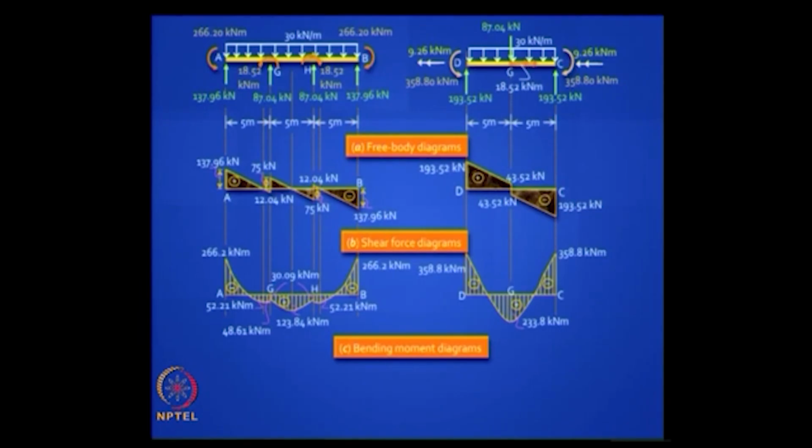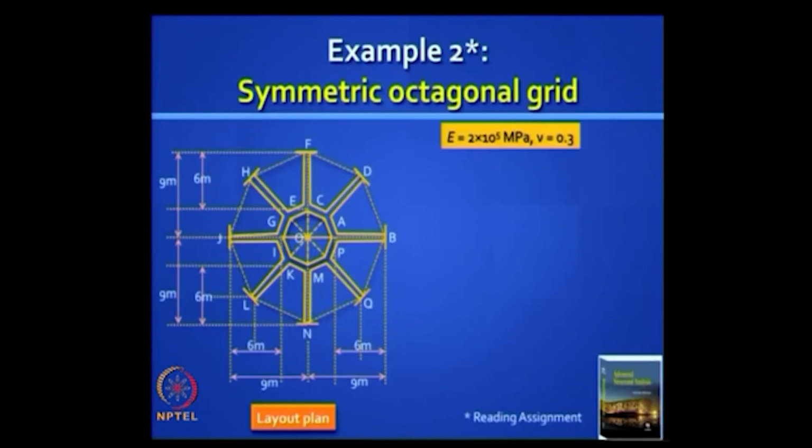You will have jumps in the bending moment diagram where you have local concentrated moments acting, and you will also have twisting moments in the shorter beam. Is it clear? So this is all you need for a design. You have got the full beam, you have got all the internal forces, you have got the support reaction, you have also got the maximum deflection. So it's a very powerful way of solving such problems.